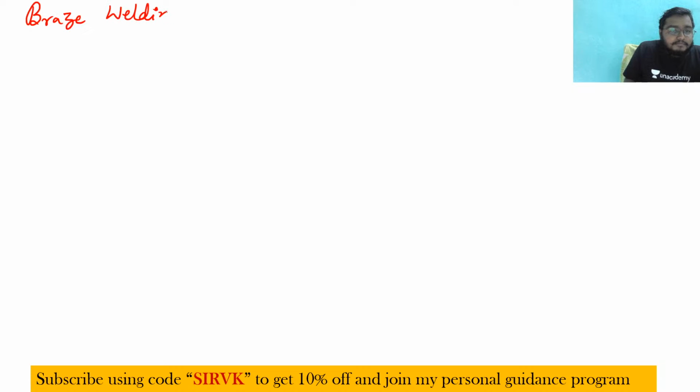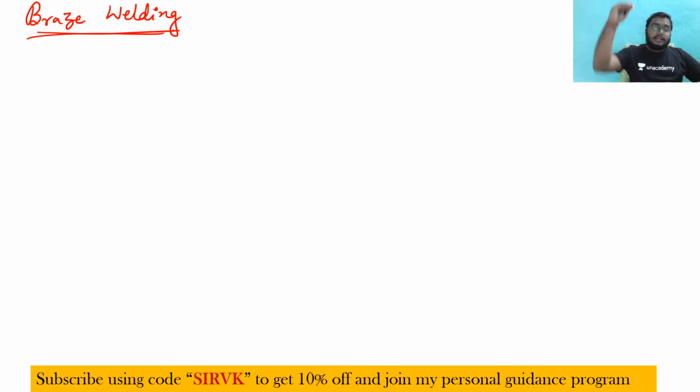Now see, by listening to this name you may be thinking, hey sir, you already told me about brazing and now you are writing braze welding, why, is there any difference? Yes sir, there is a difference. What is the difference? In brazing, the filler material was entering with the help of capillary action. The process was capillary action, but here they are entering by means of gravity force.